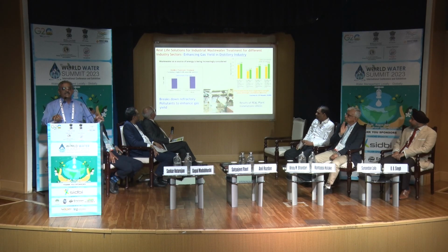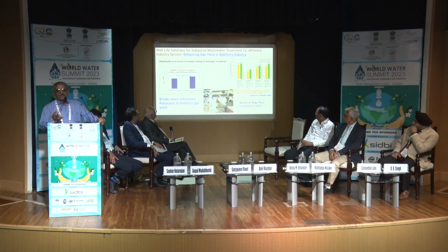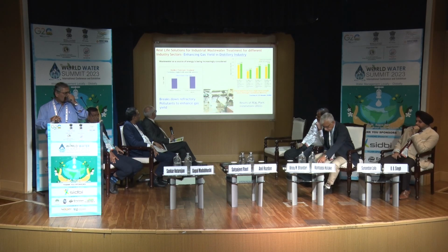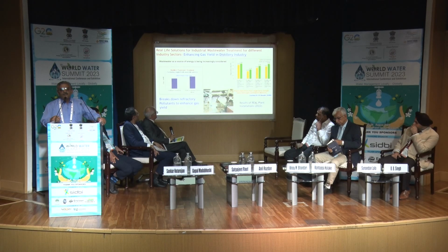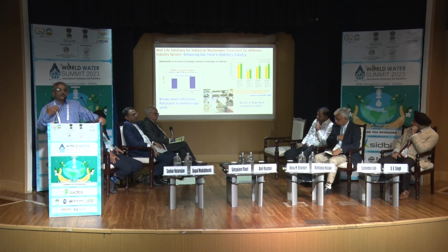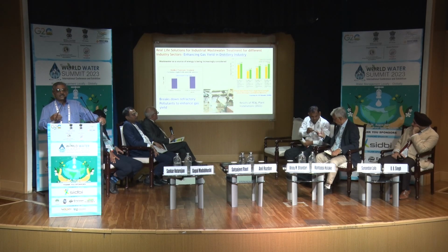Now this technology is getting more popularity in the distillery industry specifically, because the effluent generated by distilleries is very strong in COD, BOD. You have COD close to 1.5 lakhs and BOD more than 50,000. So here we have biological treatment in place. Here we are not employing this technology for removing COD. What we are doing is converting part of the COD into BOD. So that generates additional gas. So we get more than 20% increase in the gas yield.